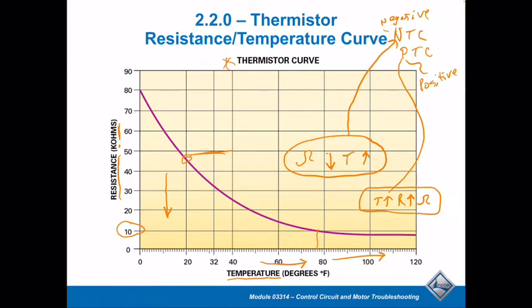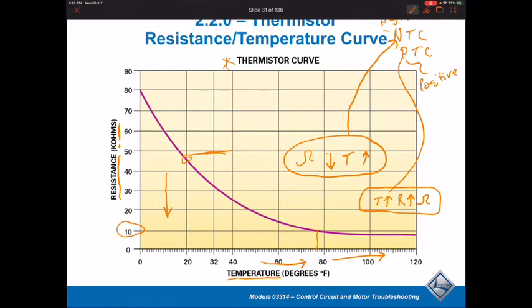let's say the sensor is very cold, the resistance is low, and that allows me to get, let's say the temperature drops, the resistance would indeed drop as well, and that would allow for more current to flow to the start winding. So in that image, that's really what they're referring to. They would put that in parallel with a run capacitor for starting a compressor. So that's one of what they call a hard start kit, but it's probably better defined as a PTC start assist is really what it is.